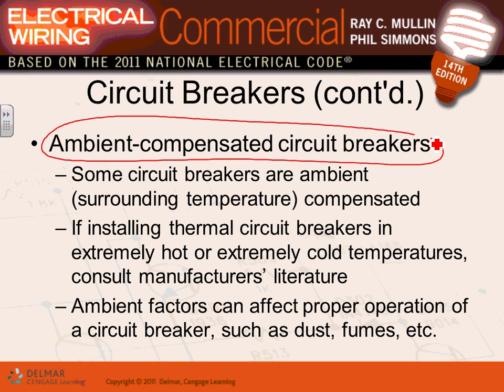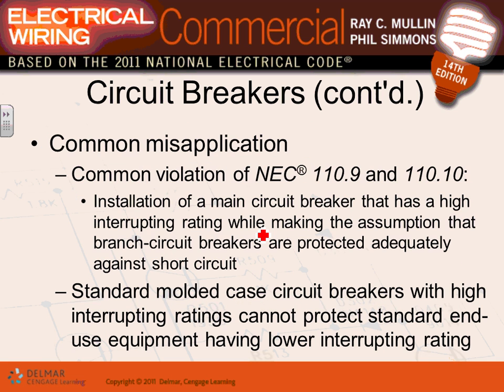Extremely hot or extremely cold, consult the manufacturer literature. Again, extremely hot and extremely cold, you have to readjust your circuit breakers. Why? Because circuit breakers can open when they're not supposed to, and not open when they're supposed to, because of the temperature.